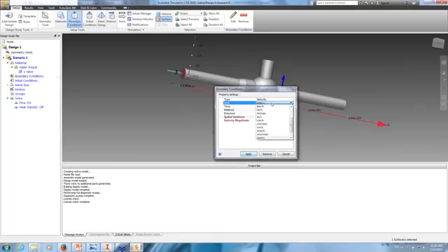You can change units, so you can have a different unit for each and every boundary condition. So you don't have to follow the overall unit system in the model, and hence you don't have to make conversions on the fly and subject yourself to possibly making a mistake with the conversion.